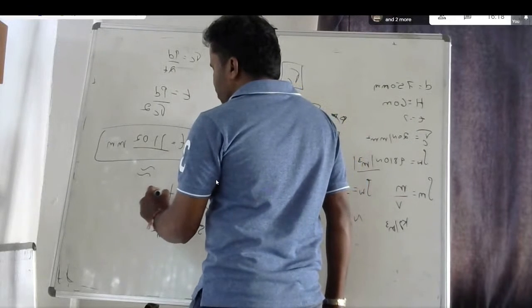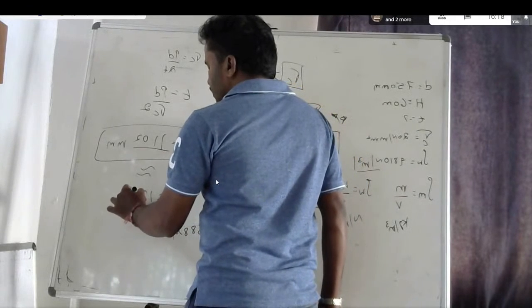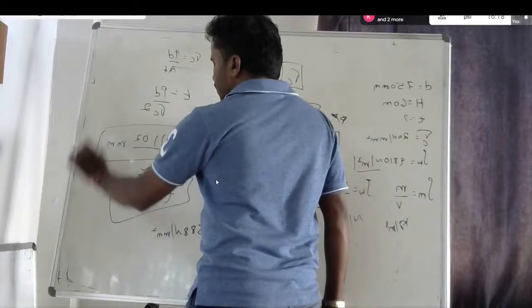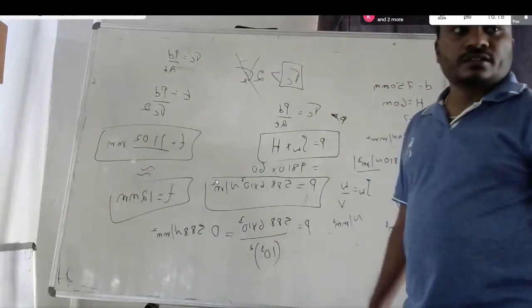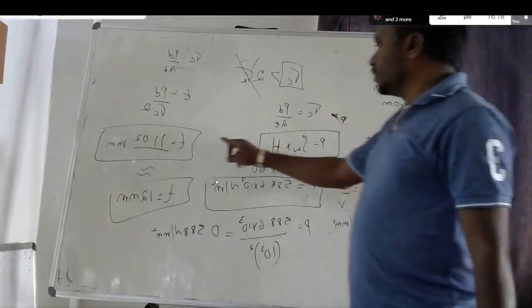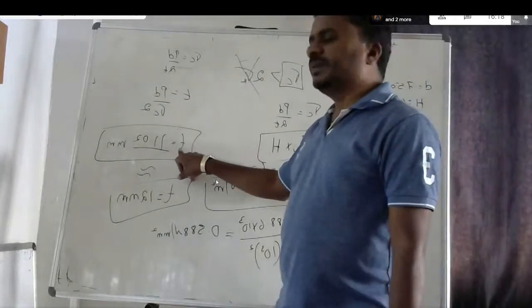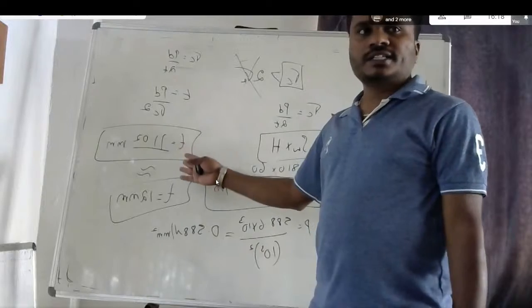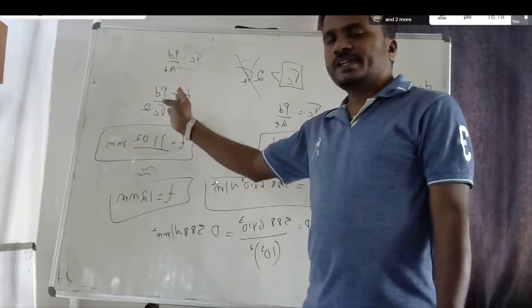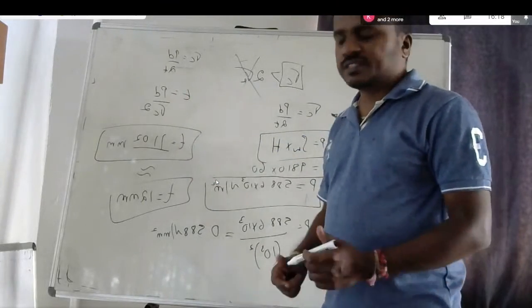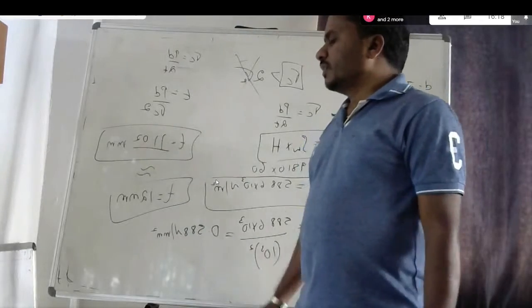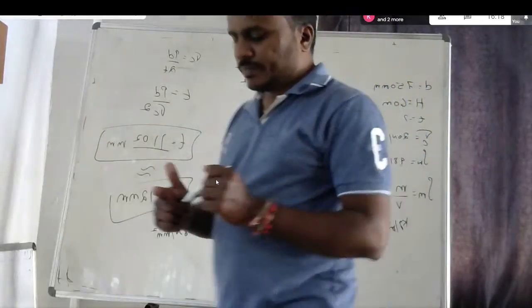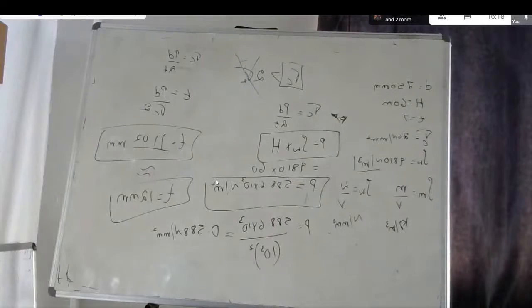We round up to the next number, that is 12. We should not go lesser, because to withstand this pressure at this stress, this should be the thickness of my cylinder. If you take less, it is definitely going to fail. Therefore, always take the higher number, on the safer side. So the next round number is 12 mm. Understood? Yes, sir.